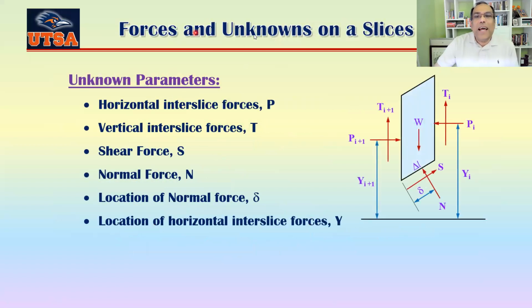Now, forces and unknowns on a slice. Okay, I'm just trying to show you the free body diagram of the slice and what forces are working on that free body diagram, because I need to solve the static equilibrium for each of those slices, and they have to be in equilibrium to make sure that this one is stable. Okay.